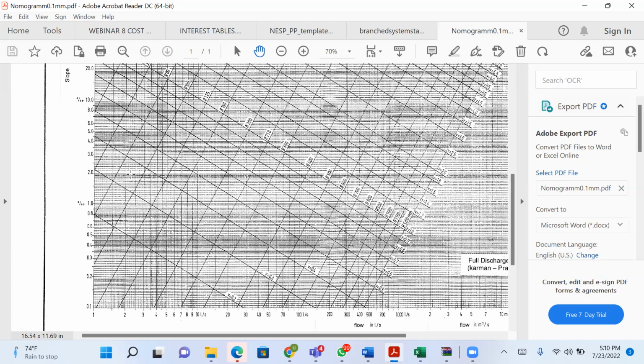But later, I'm going to show you that in choosing the higher one, you must not over design. So you must do what we call percentage filling. You need to check how full is the pipe, because the standard is that your pipe must be 70 to 90% full. So don't go and design a pipe that is carrying capacity at 30% or 40%. You're a bad consultant, you're a bad designer. Your pipe must carry 70% of its load or up to 90% of its load. Only 10% free board you should give.